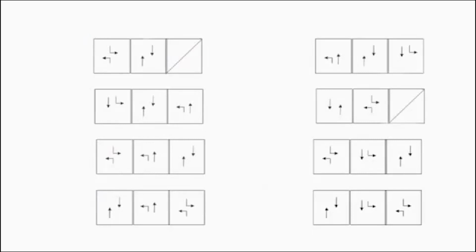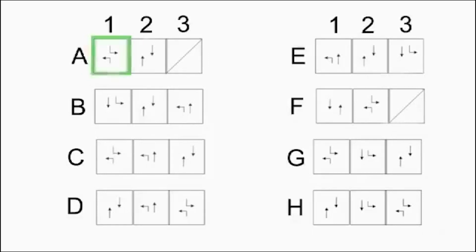For instance, on the top left, I have the northbound left turn and the southbound left turn. That is a state. In a digital architecture, I can call it a name. Here, I'm going to call it A1. And any time I want to bring up A1, I can do that. If I want northbound through and southbound through, state F1, if I wanted that, I can call it. And it's going to show up just like punching the buttons on your remote on a TV.